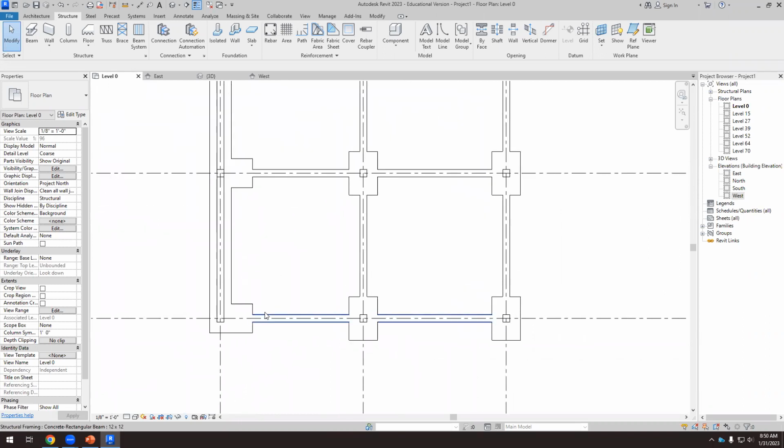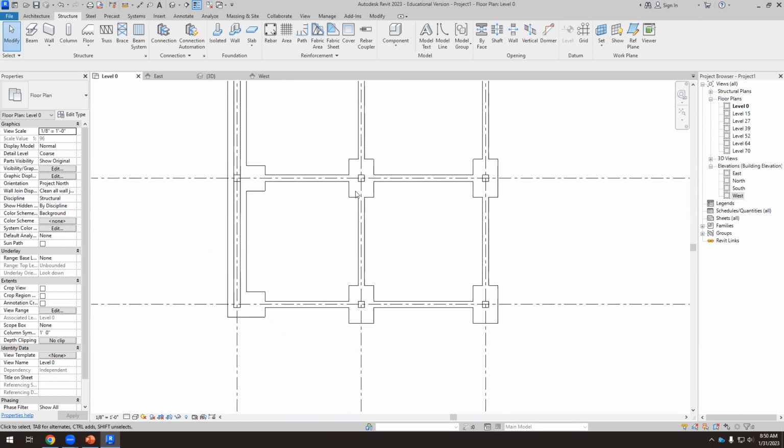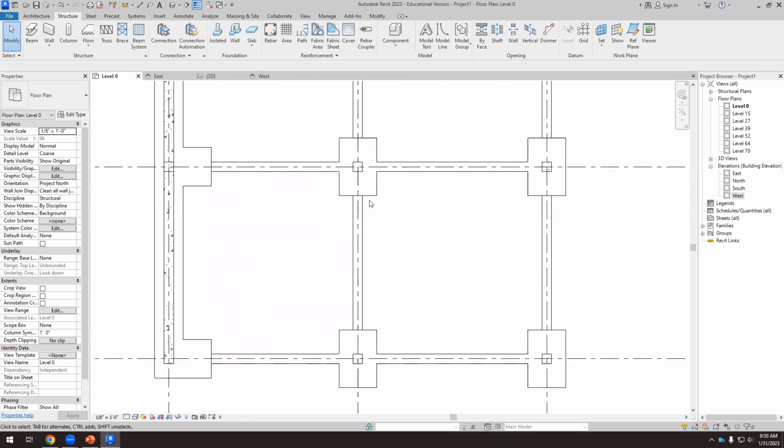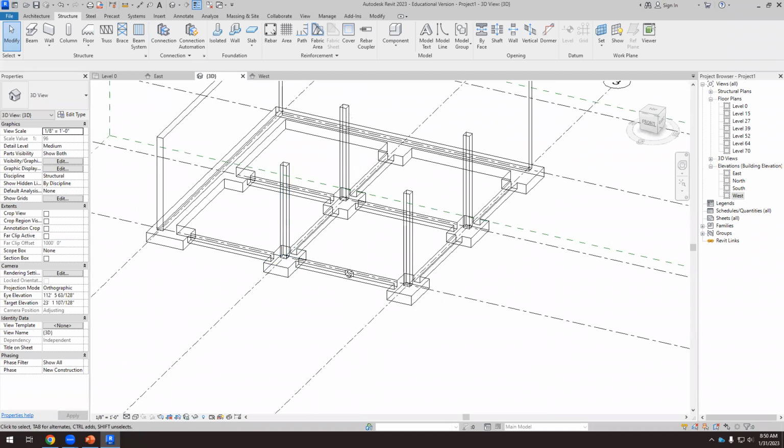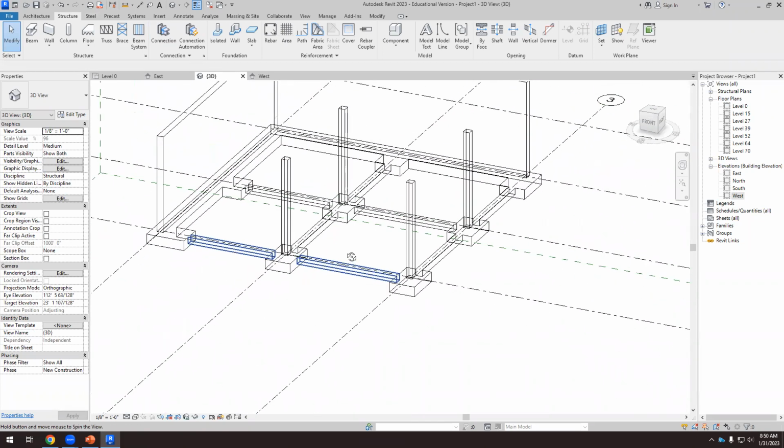Anyway, make sure that the foundations are well calculated, and not only the calculations, but when you go to the site, make sure that the reinforcement is in the right place and the size of the footings is the right size, because it's worth it. Okay, so you will save a lot of issues if foundations are good enough.